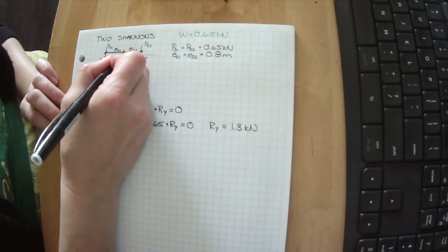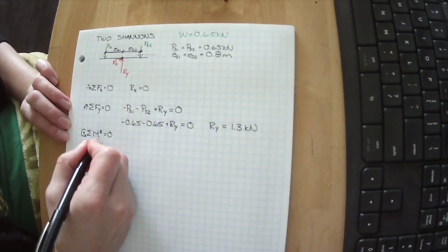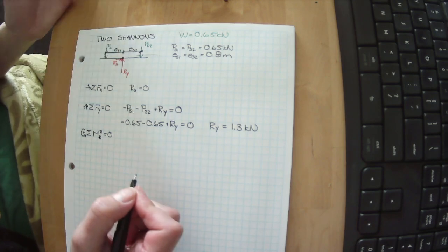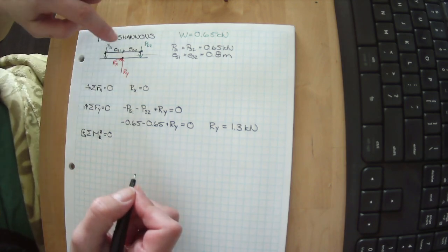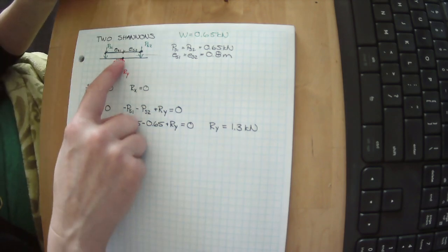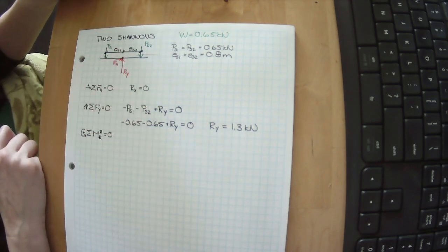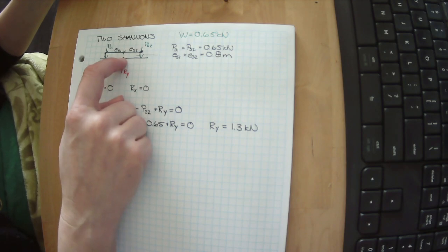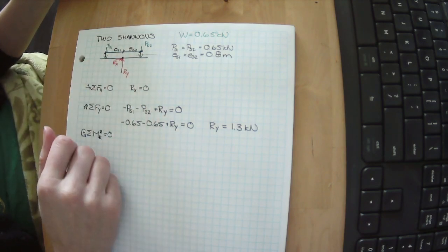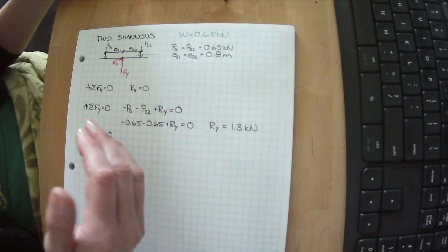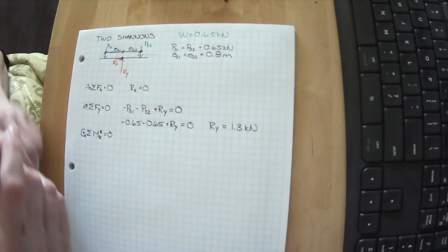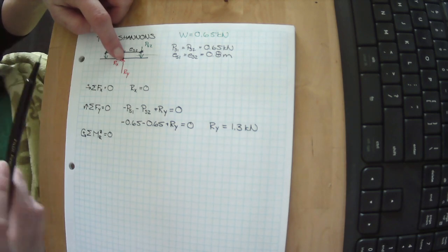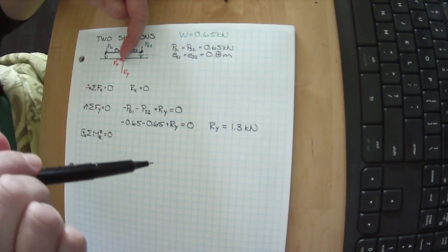Let's talk about spinning this object right here. We're going to talk about spinning it about our point R, or our reaction. There is no moment reaction there. We just have two things causing this to spin. Does Ry cause our object to spin about this point? No, it's passing right through the point that we're supporting it on. Does Rx, if we're spinning about this point? Rx doesn't cause it to spin, because to be a moment, you need a force and an eccentricity. But about this point right here, PS2 is causing it to spin in this direction, and PS1 is causing it to spin in this direction.